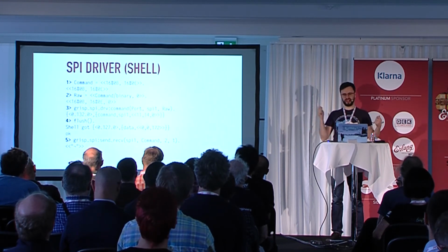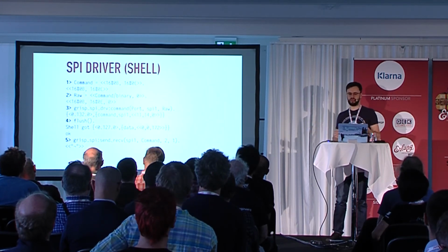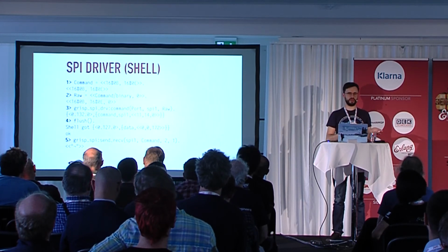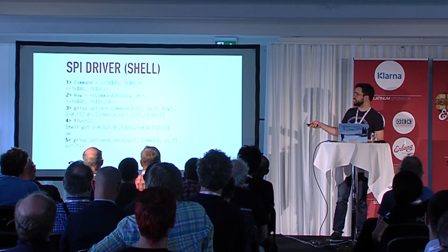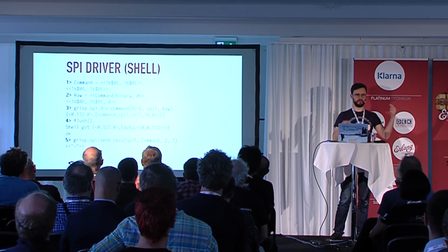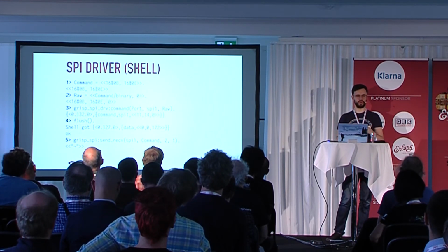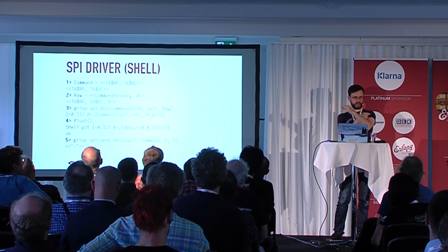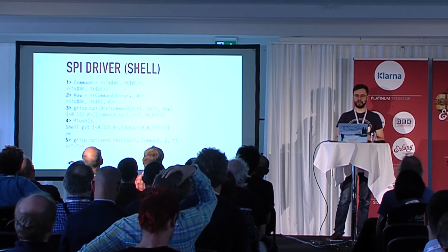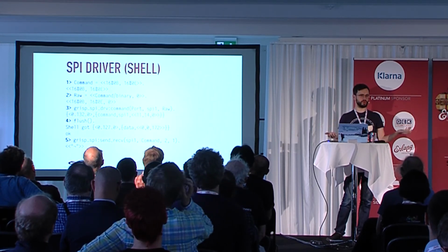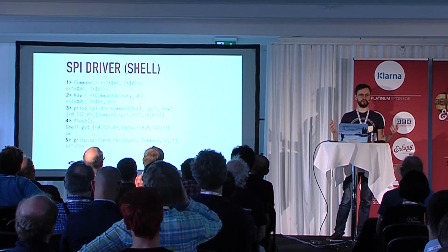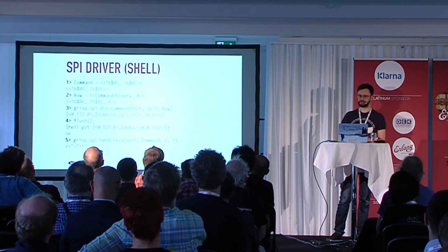But we also want the value of the register. If the value of the register would come in the second byte, the PMod wouldn't know which register we wanted to read, because that's the byte that's currently in transit, right? So we have to wait for a third exchange where the value actually comes. That's why we pad with 0, because we have nothing more to say to the PMod, and we're just waiting for 1 more byte from the other side.